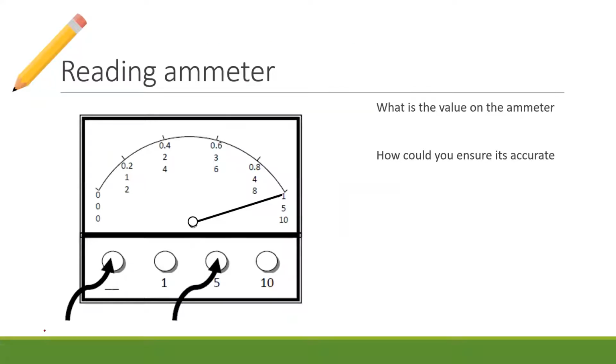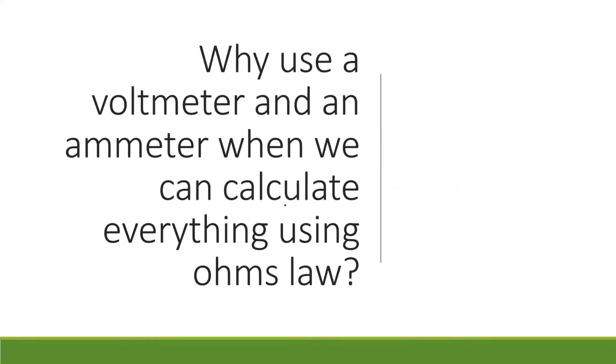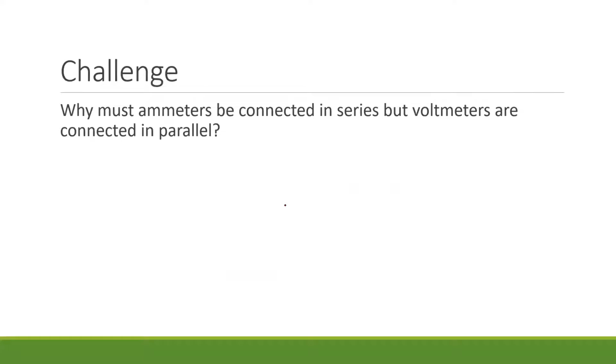We talked about how you read an ammeter, and a little bit about how we have multiple scales because you can have circuits at different points. And I talked a little bit about this idea of maxing out a scale. This is maxed out at, in this case, 5 amps, but it could be more than 5 amps. We don't know because the scale is maxed out. Then we talked about why it has to be in series versus parallel, and about short circuiting things and students destroying ammeters.